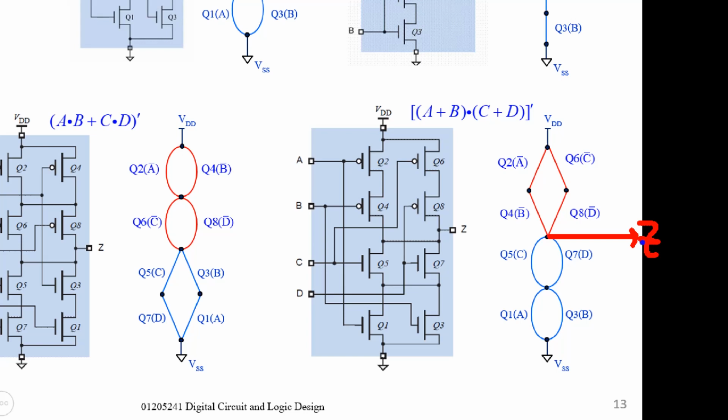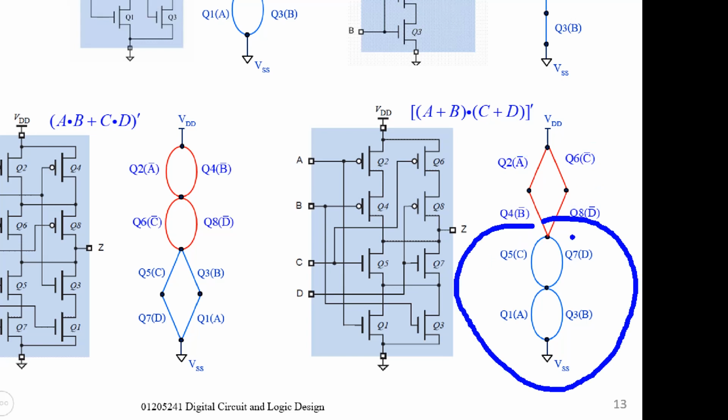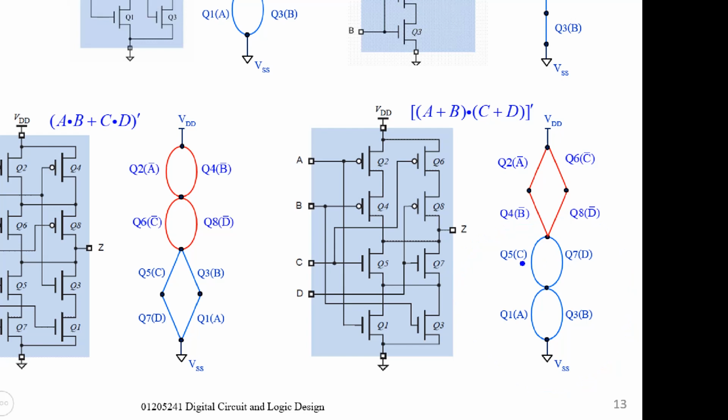One thing you must be careful about is active low. So don't forget to invert each input parameter. And if you consider the lower part of the circuit, each input is an active high signal. But don't forget that if this one turns on, you make the output become 0, right? So for your function, don't forget to invert all of this to make the output become 1.